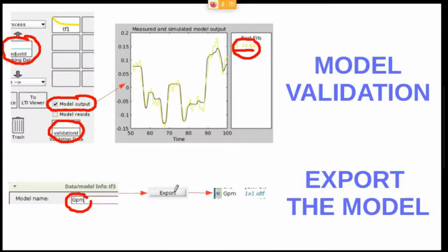Then you click at the bottom left part of the window, you will see that there is an export push button. And once you click here, a new variable appears in the MATLAB workspace, and it is an identification transfer function object, right? Its dimension is 1 by 1, just because you can access the numerator, the denominator, and the like, just like a general structure in MATLAB.